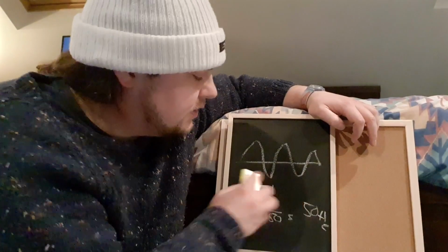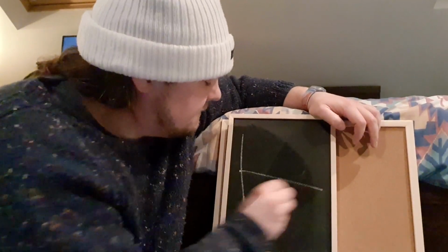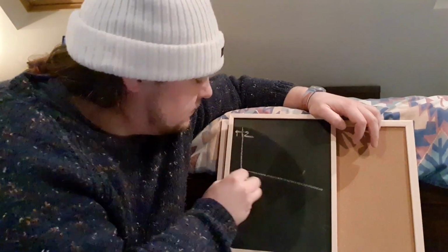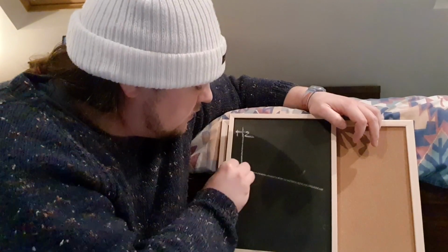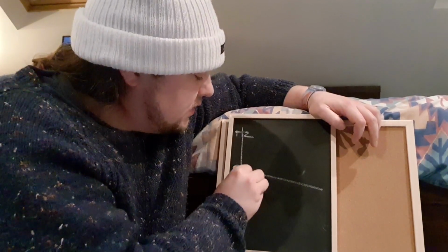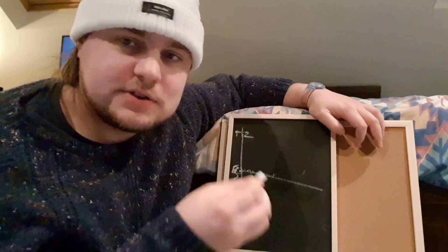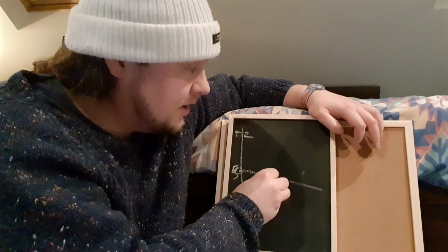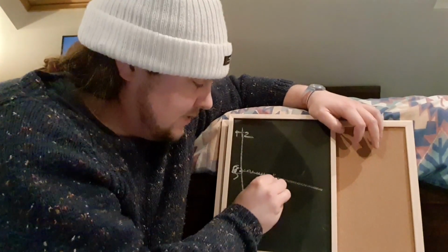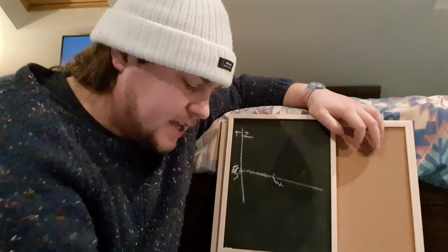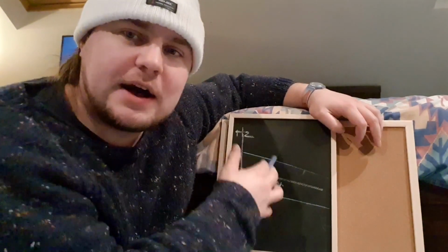Okay, so if we draw a diagram where we measure the grid frequency, this is now hertz. That's 50. Then we want to stay there. And like I said before, if everyone starts using electricity at the same time, the frequency would drop. So it starts going down. And then basically there are limits on where we'll allow the grid frequency to go.